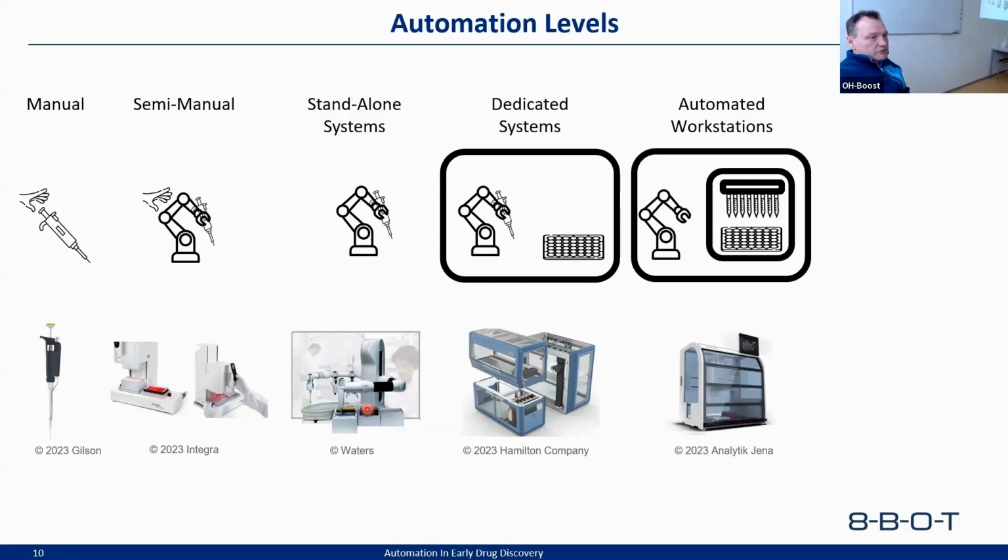Then you have the automated workstation. The line drawing here is a little bit difficult. This one is a pure liquid handling station. And this one here is a Cybio Felix from Analytik Jena, which is more or less a small screening station, something like the OT-2 robot that Nicole showed before. Here you have different options: magnetic bead extraction, shakers, warm plates, whatever. You cannot do everything with this device, but you can do a lot, starting from hit picking, automatic tip change, 96-well, 384-well, 1536-well plates, whatever. I would say about 100 to 200,000 euros, depending on the parts you try to integrate there.